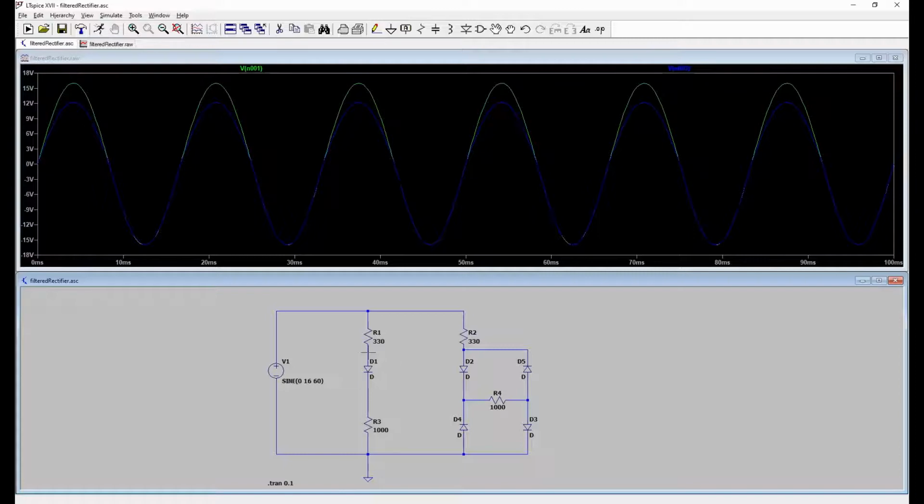And just like with the oscilloscope traces that you probably have already seen, on the half-wave rectifier, the voltage is different from the positive half cycle, where it is conducting through this 330 ohm resistor, versus the opposite half cycle, where it's not conducting. So on the positive cycle, there's a drop in the voltage. On the negative cycle, there's no drop in the voltage.